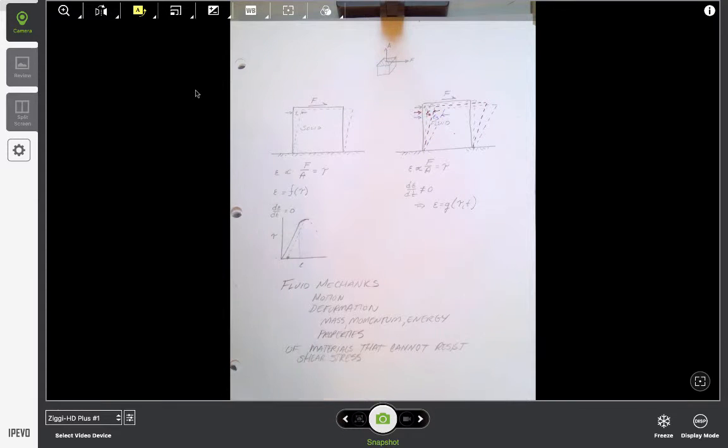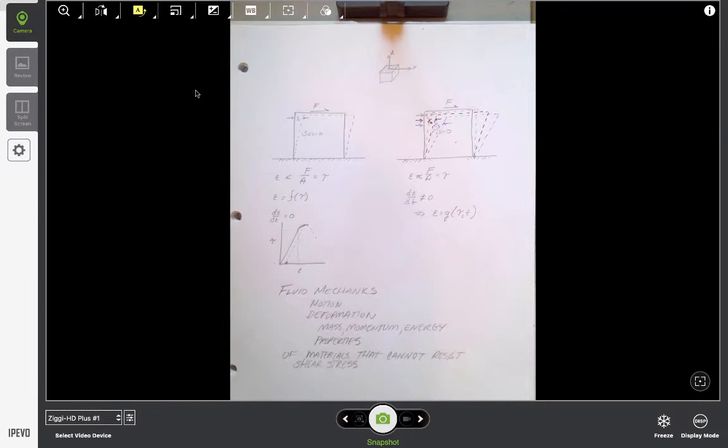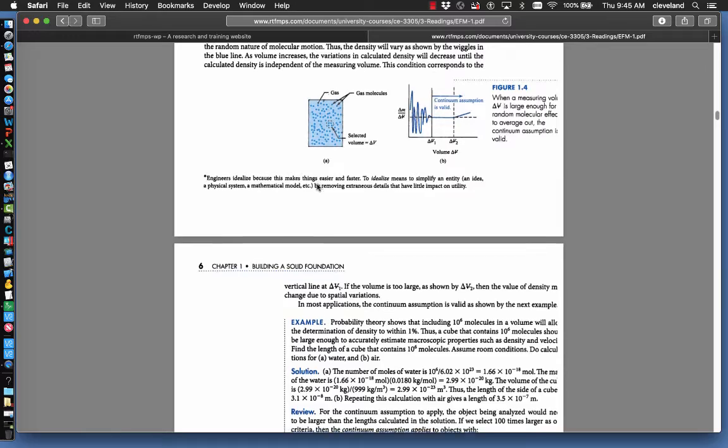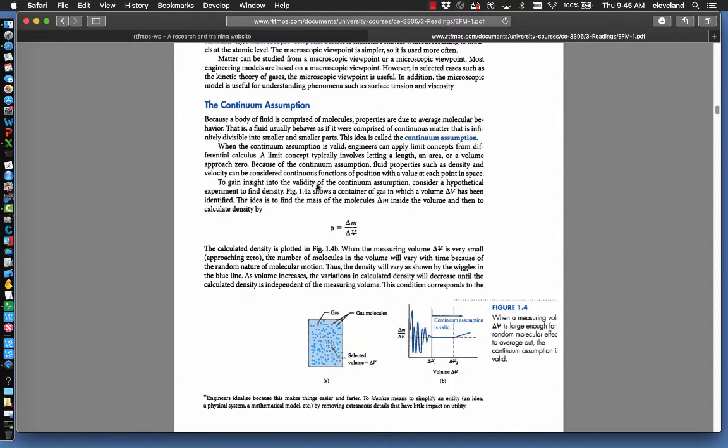Okay, the calculus of fluid mechanics, the mathematics of our book, uses continuously differentiable functions, and that use implicitly assumes that fluids are continuums. So we go back to the reading, and we have some discussion on continuums. The continuum requires a concept of an averaging volume that's large enough for continuum behavior to exist, but small enough so that we're not picking up continental size differences. And I have a nice sketch to illustrate that.